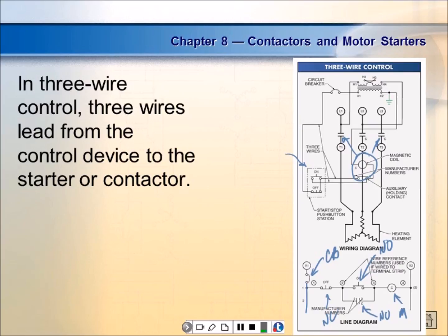And why do I know it's not a motor starter? Exactly right. There's no overload contacts on the L2 side. You know, here, Heath. So there's no overloads on the other side. There's only one thing that's allowed between the load and L2, and these are overload contacts. So we have the overload heaters that are up in the motor circuit, right? You understand? But the contacts are going to be in our control circuit. Are we okay? Any questions?